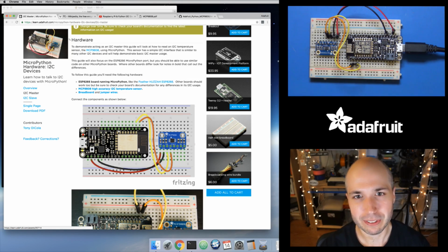Most fast devices use a SPI interface where you can use the clock at whatever speed you want, usually multiple megahertz. Whereas with I2C, there's a fixed clock rate. It's usually 400 kilohertz, and I think there's a 1 megahertz high speed mode. So it's usually a little bit slower with I2C, so you don't have massive LCDs with huge amounts of pixels to push very quickly. But anyways, with the ESP, you have a lot of flexibility.